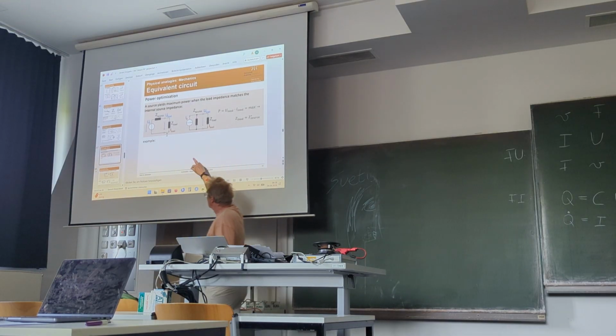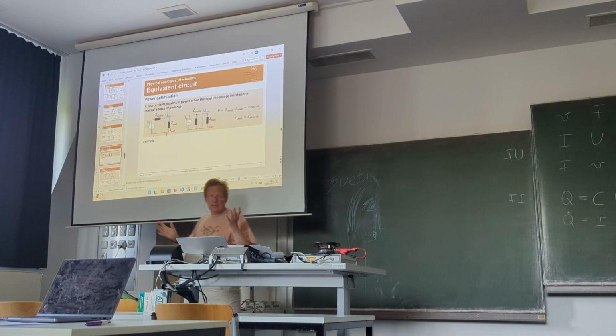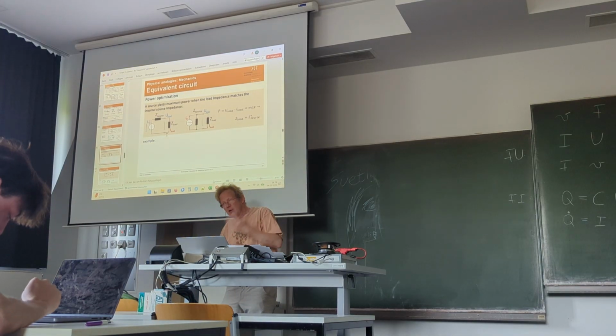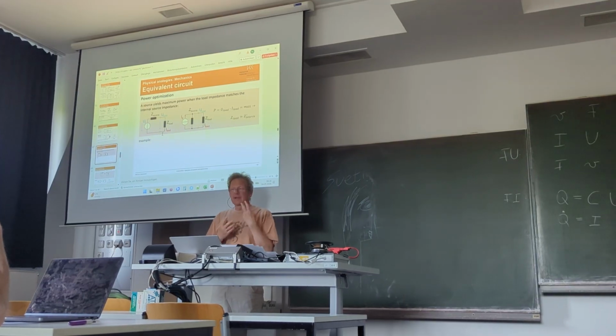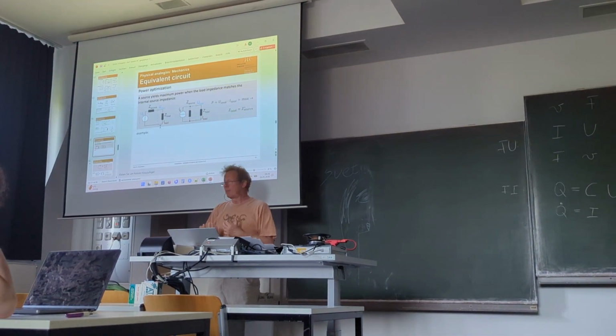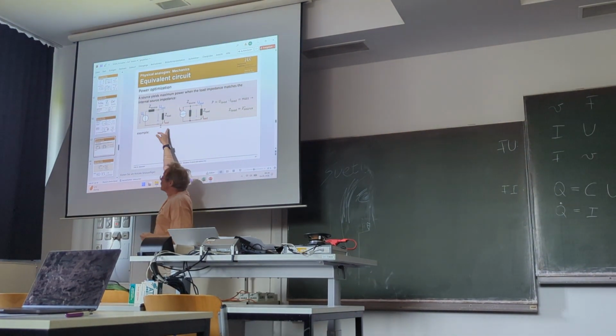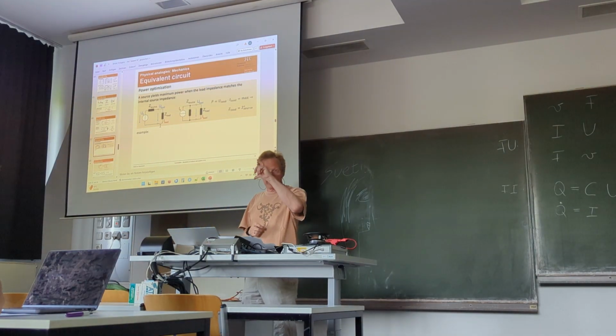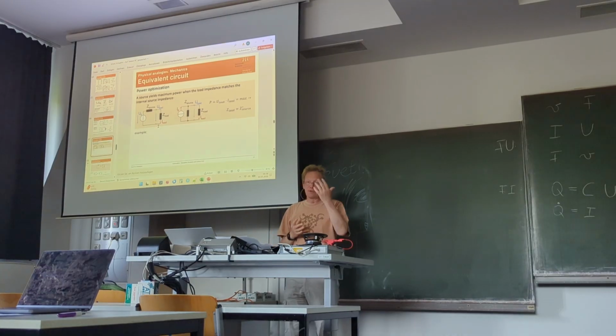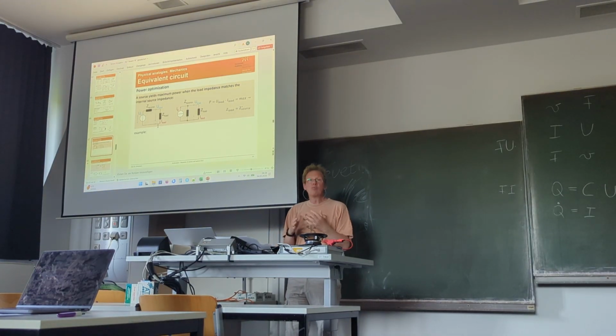If your load is merely a short circuit, you will get a big current, but the voltage is going to zero, so you have no power. If your load is very, very large, then you will get a maximum of voltage, but really no current, so again, no power.